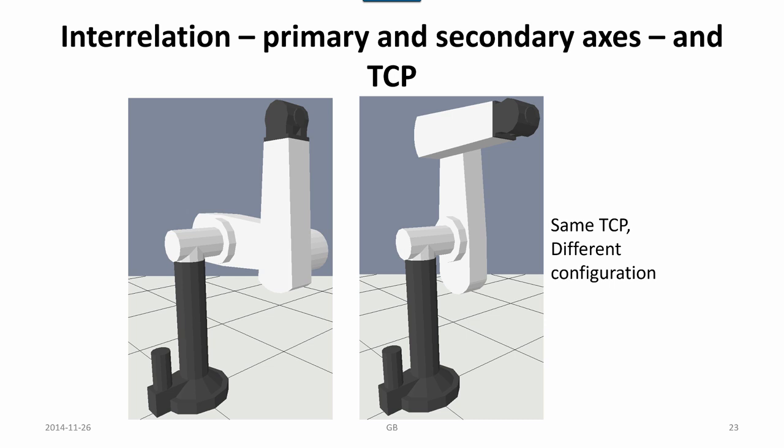And quite often one has to actually decide what type of configuration should be used to reach that, and then try to have the same configuration for the whole task program if possible, or at least for some part, so it doesn't mix up different configurations, because then it has to switch over and might come into collisions and also run the servos, which takes time to come to the next type of configuration, usually by turning 180 degrees of some servo drives.